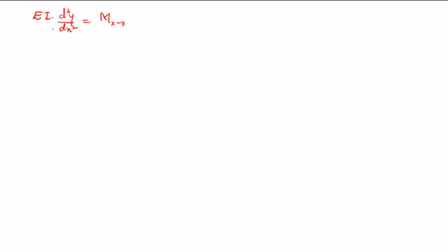Now if I integrate this equation, EI dy by dx equals the integral of Mx dx. What is this term? It is the area of the BMD diagram.